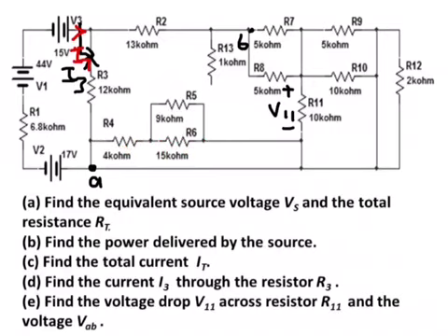This one is in series with the parallel combination of these two. But this whole branch is connected between this point and this point, and these two points are shorted by this piece of wire. So this whole branch will disappear. I don't need these resistances in my circuit. They do not contribute anything to the circuit because they are shorted out. So I can redraw the circuit and eliminate them.